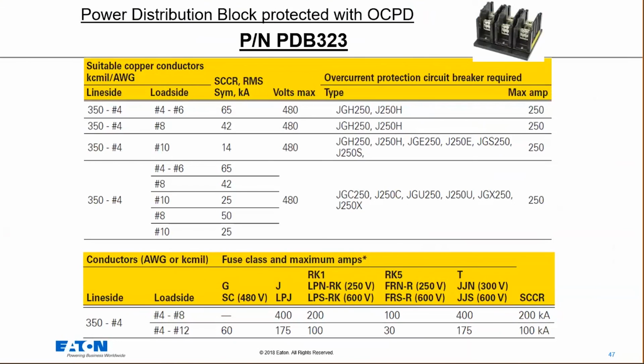And the reason for that is, when we test them, maybe they pull away from the terminals, not necessarily going to explode or cause maybe an arcing. Well, they could potentially cause an arcing issue, because if they do pull away from the terminals or do something else, then it could obviously cause a situation where we're arcing and causing a shock hazard for sure.